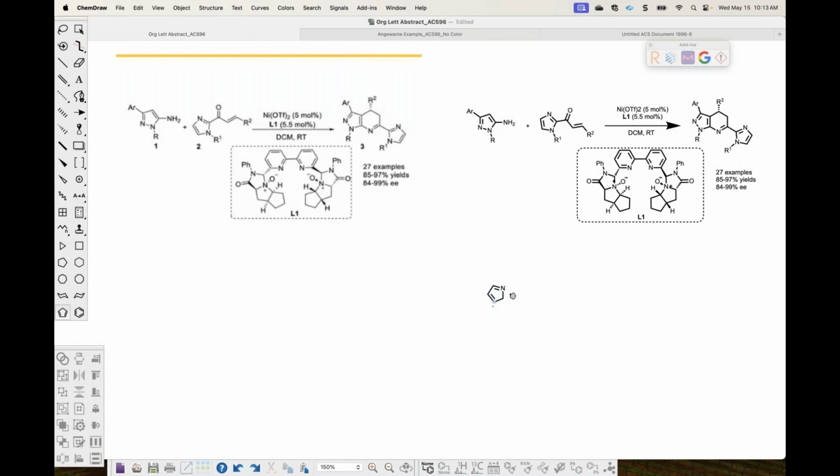Oops, I did that wrong, actually. Let's come over here, put my nitrogens on. I'm going to press 1 to add an alkyl bond here, and then I'm going to press R. And that's going to put just an R there. If I want to actually change that to an R1, I can press Enter. And what that's going to do is put me into text mode, and I can press R1.